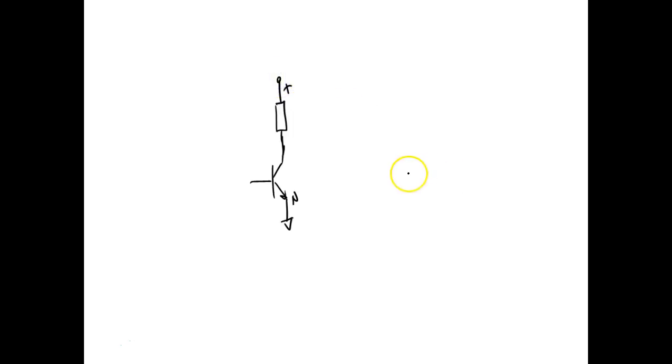Understand? Now an NPN sensor, what they do is this guy here is pointed toward the negative DC, and then my load is connected right here. So when we put a 0 right there, this guy here turns on. But over here, since this guy here is providing the negative, then this guy right here has got to provide the what? Positive.